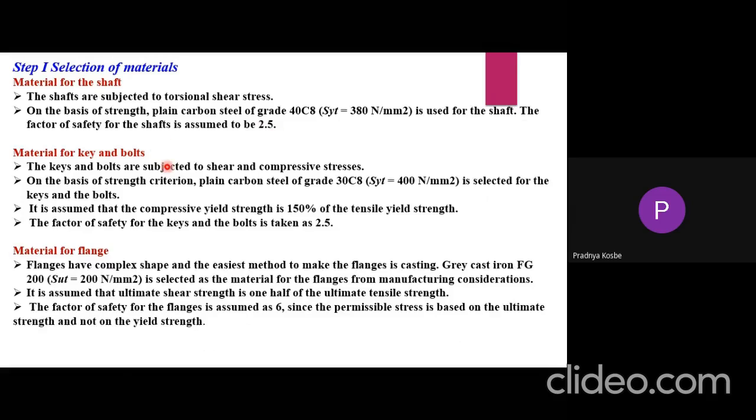Then material for key and bolts. As key is in contact with hub and shaft portion, obviously that key will undergo shear stress as well as compressive stress.